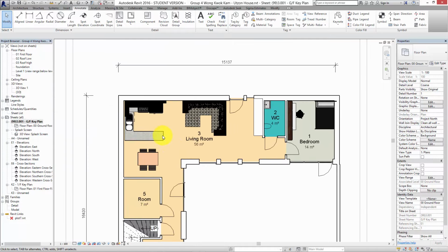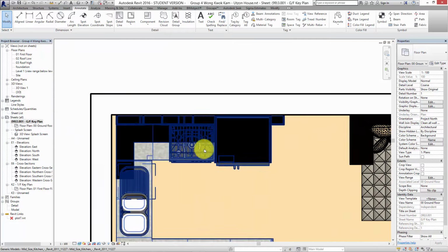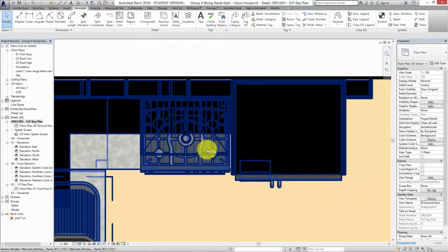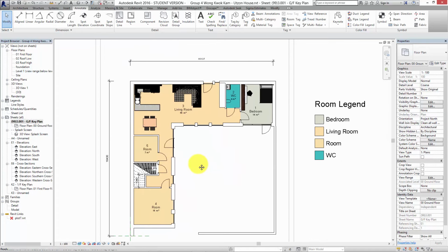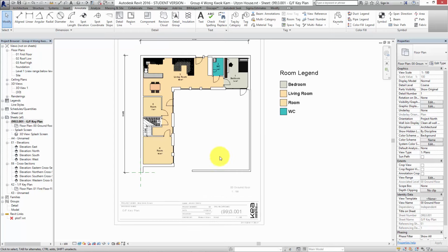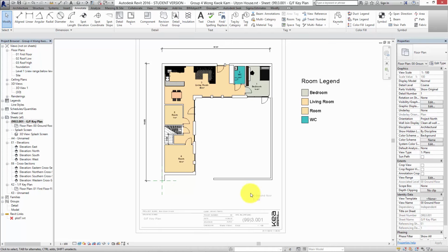So there's a few other things I would do in here. I mean, you've got many extremely detailed families in there, and they look great in the 3D view, but in the plan view, they just attract too much attention. So I would remove them out. If I was to work a little bit more on that, put some surfaces in there, make sure enough furniture is in there to really describe the activities in there, that's what we call a concept stage plan. Okay. And after that point, next week we'll get into a technical stage plan, which has got different settings and so forth.